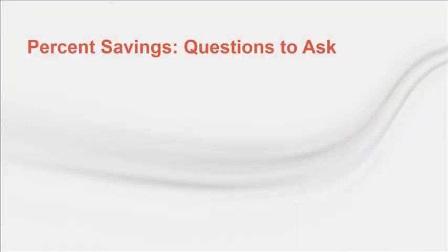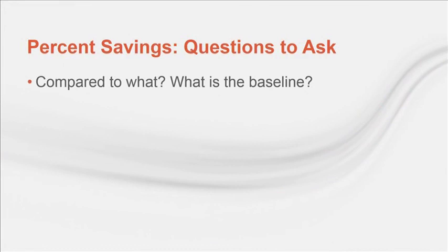So in examining such savings claims, the first question we should ask is, compared to what? If we take a system designed to today's energy efficiency requirements, using today's controls, and perhaps even with lower capacity because buildings are more efficient, but we make our baseline an unoptimized system from the 1980s, well, if we can't get to 30%, we aren't even trying. So make sure that comparable and current systems and technologies are used in both the base and comparison system.